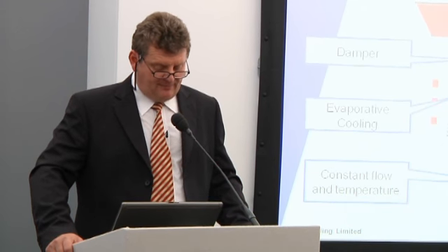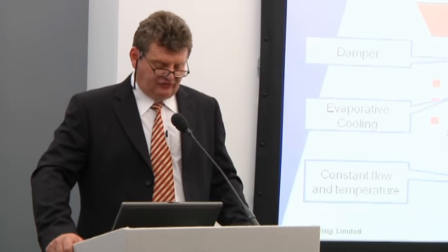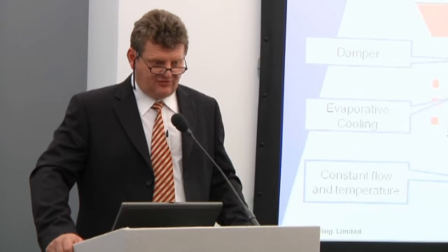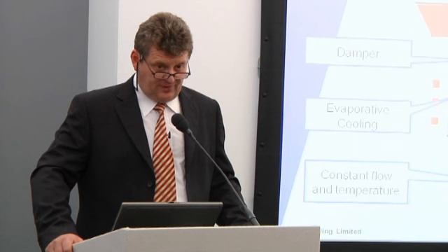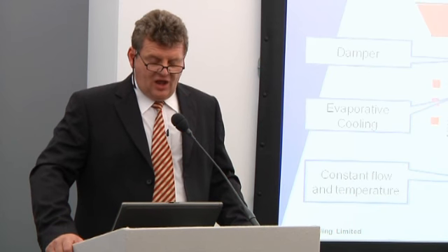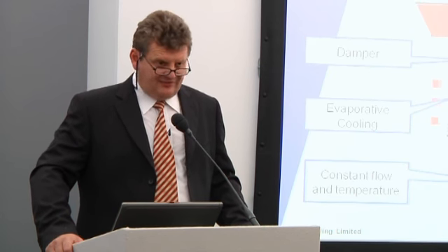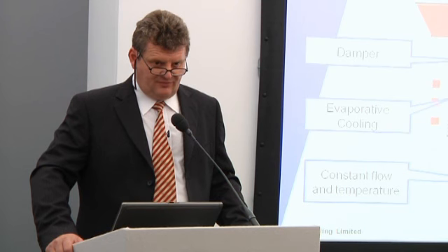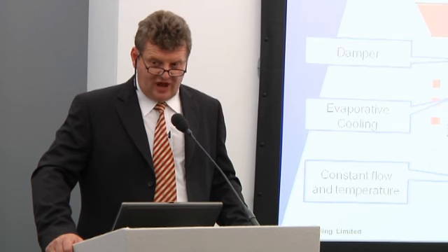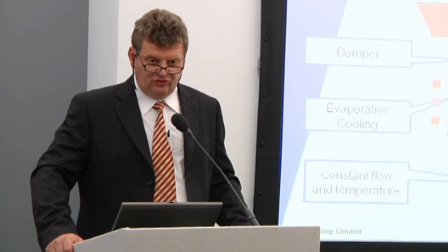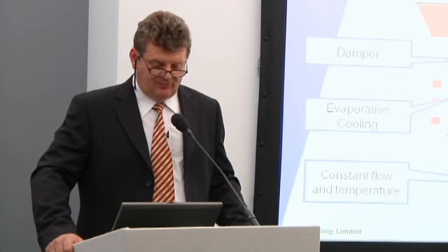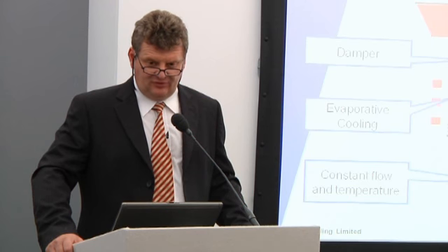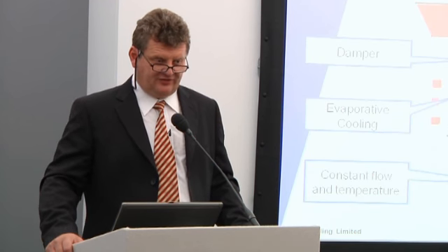There we have a damper which allows that hot air to come back into the centre of the cooler and mix with the ambient air which is going over those filter pads. For 90% of the time we will be running on a fresh air system, just using the hot air to warm the ambient air up to give us compliant conditions going forward, typically about 20 degrees centigrade.